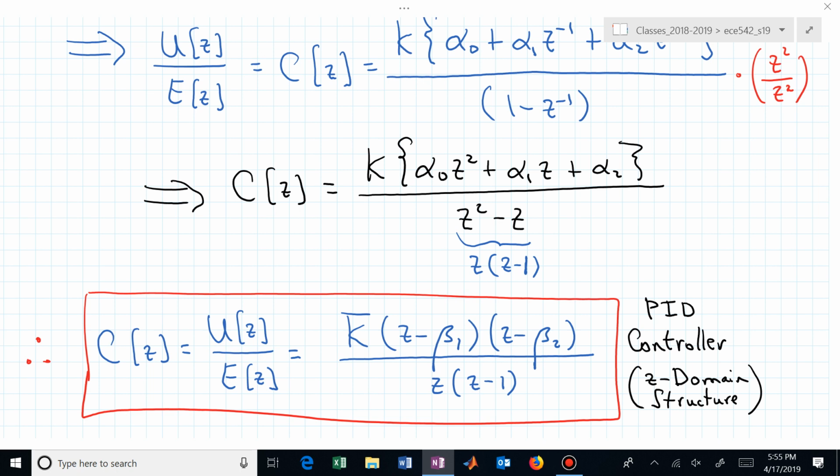On the final exam or on your homework, if I now say design a PID controller, you don't have to go through and find the integral time, the derivative time, the gain. You just now sprinkle a pole at the origin, a pole that's equal to 1. Those are fixed. You don't even get to sprinkle those. You just fix those. And now you get to locate 2 zeros.